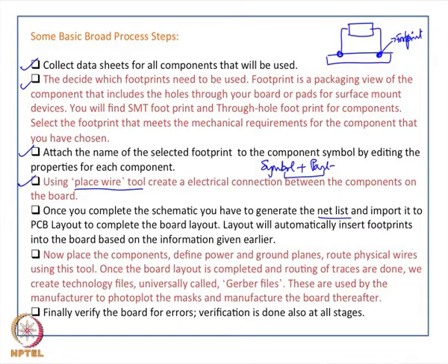Once you complete the schematic, you have to generate that netlist, which I said is very important, and import it into the PCB layout to complete the board layout. Layout will automatically insert the footprints because you have already tagged them with the symbol. So, once this process transition takes place, the information is also moved over into the layout section.